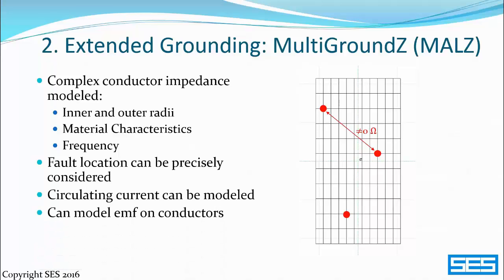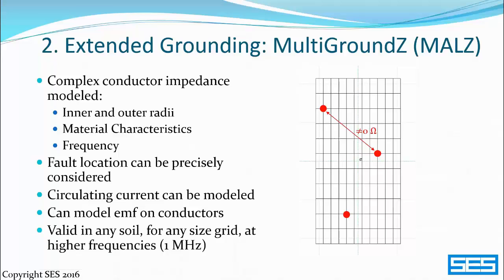An additional useful feature is that we can model EMFs on conductors from a source of inductive coupling, though the magnitude of the EMFs needs to be computed elsewhere. The improvement means that we can now essentially accurately compute any size grid in any soil, even in frequencies up to 1 megahertz.